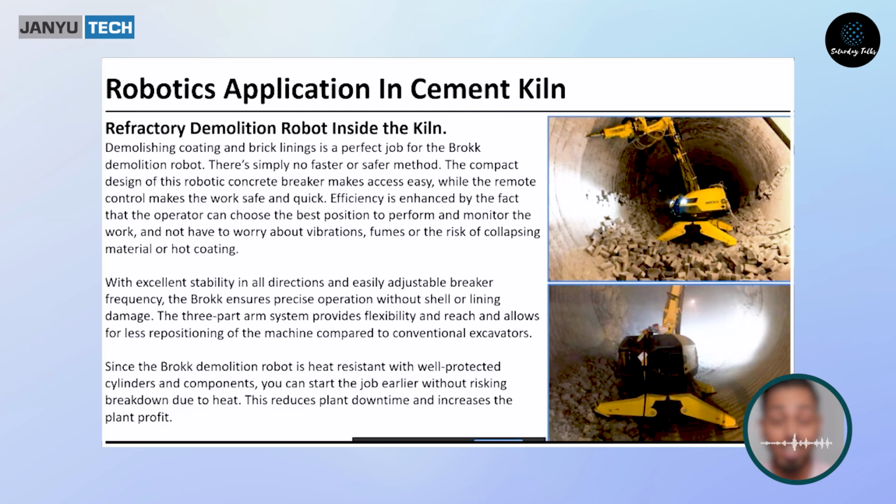Snowman formation inside the kiln. There are two frequent issues in most of the kilns. One is snowman formation, for which we have to stop the kiln totally, cool it down, and get inside with people, and either use a water gun or manually break it.